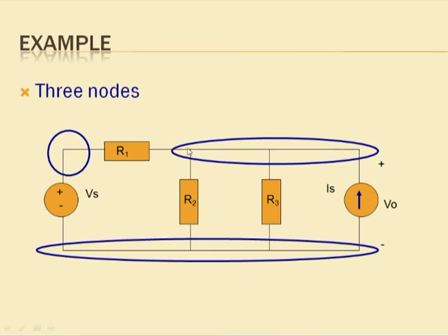The second one, at this point. Someone may think that at this point only two circuit elements are connected, R1 and R2. But it is not true. Why? Because you can say that the R3 is connected with this line and this line is nothing but, as we discussed, some connecting wire.